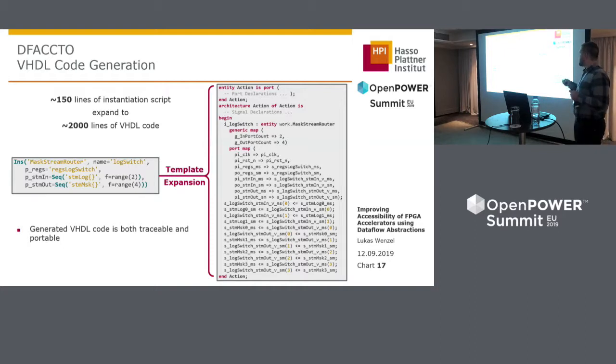So you see, much is missing from this, but just to have the equivalent of this shorter segment, we have here the instantiation of the master stream router entity, and underneath some kind of vector unpacking, because we have here a list of signals that are connected to a single port, so we have to unpack them manually, which would be quite tedious doing it manually in VHDL, but we are happy to have this kind of more concise form. As you perhaps note, it's difficult to read. The names of the signals are actually preserved in the generated VHDL, which gives us at least some measure of traceability, which we found very important to debug whatever design is coming from it.